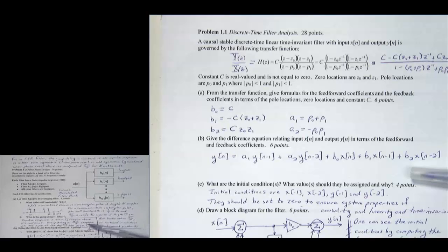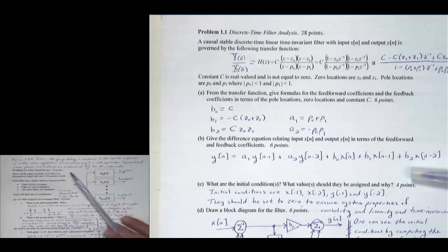Group delay in all 3 cases has to do with impulse response symmetry. If you remember, not all FIR filters have linear phase. But for an FIR filter, the group delay is constant if the impulse response is either even symmetric, which is the linear phase case, or odd symmetric, the generalized linear phase case, if the symmetry is about the midpoint of n minus 1 over 2 for n coefficients. So that's the midpoint of the FIR filter's impulse response.